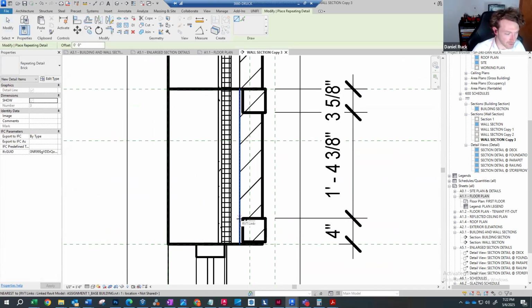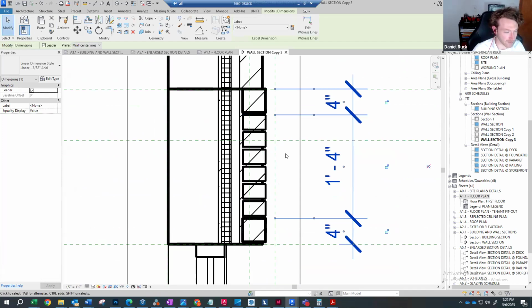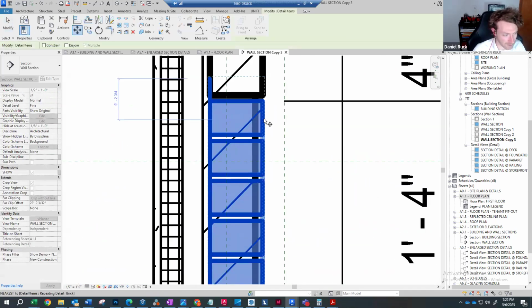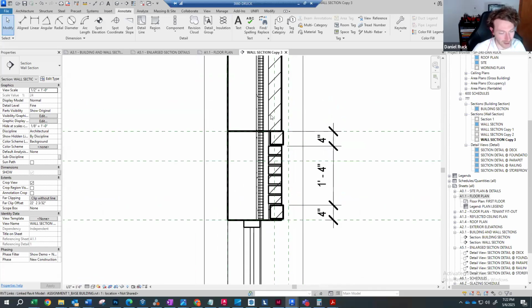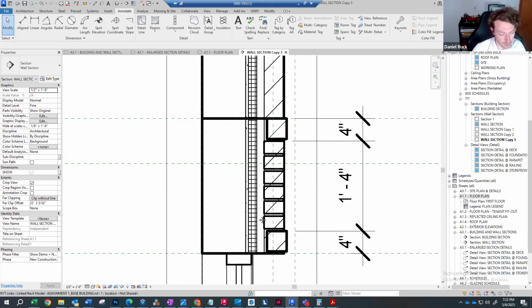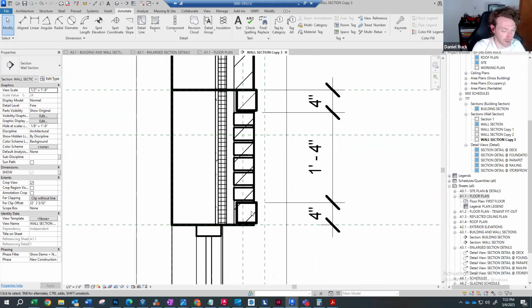We have to be sometimes creative with how we're dimensioning to these items, but this is more or less what you're aiming to get. We have a 4-inch row lock, which is a brick that's turned on its side. So we have a 4-inch height rather than 2 5/8, which is your typical brick coursing height. That's what we're seeing here.